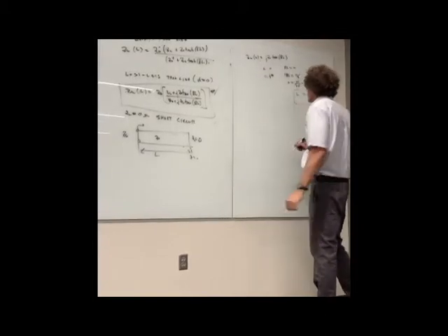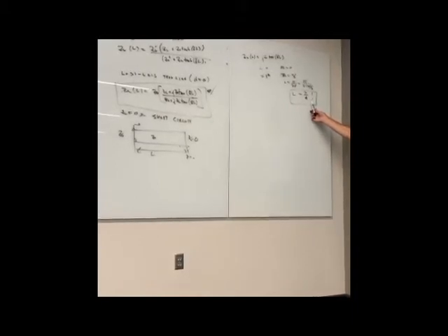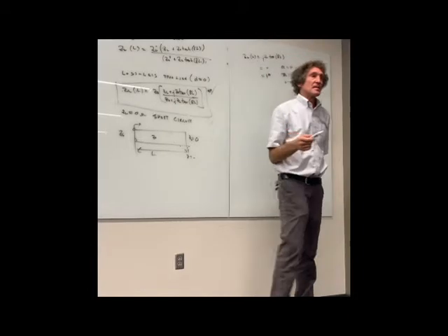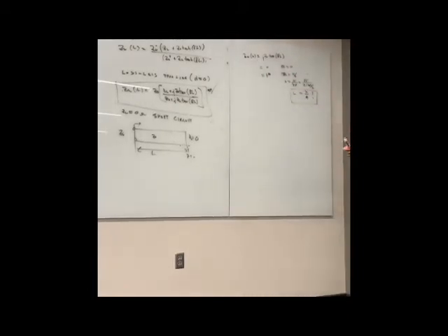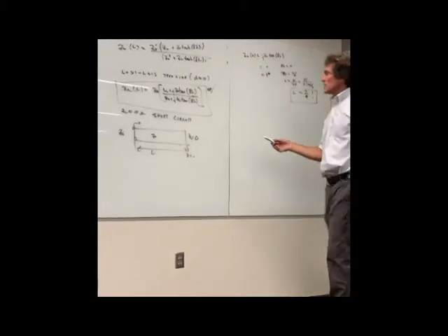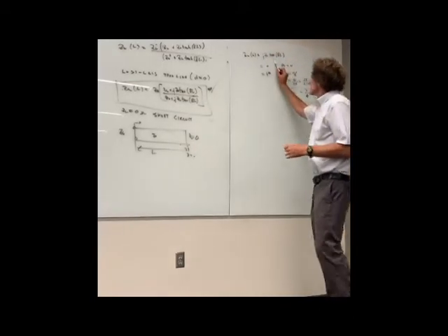This is important. So when the transmission line is a quarter of a wavelength long, now please listen. When the transmission line is a quarter of a wavelength long, and we have a short here, the input impedance is infinite. It goes from 0, when it's basically at the load, to infinite when you're a quarter wavelength away. And here's another thing that happens. What would this value be? Just look at this, when ZL is 0.